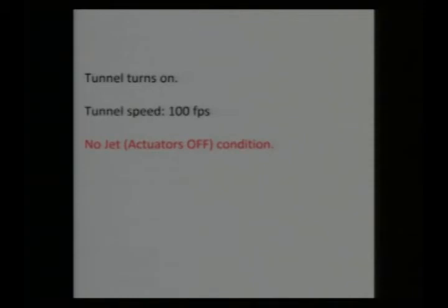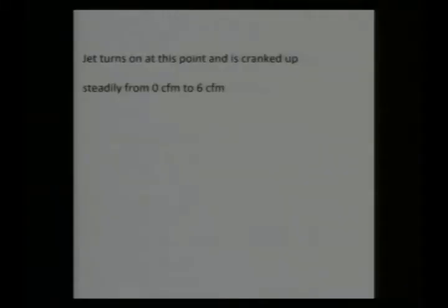So initially we begin the flow conditions without the jet, and the flow will soon begin. That's a coating of oil. So you see that this whole area is fairly separated. You don't see any movement out here, and you see this wake pointing downward, this wake pointing upwards, which shows that the flow is reattaching at this point. There is a recirculation bubble that goes up there, and then the flow managed to go downstream.